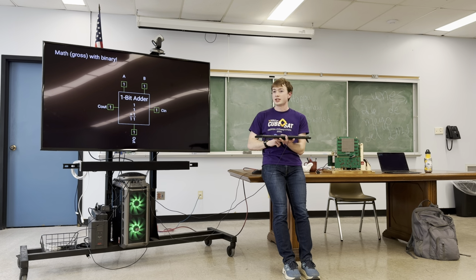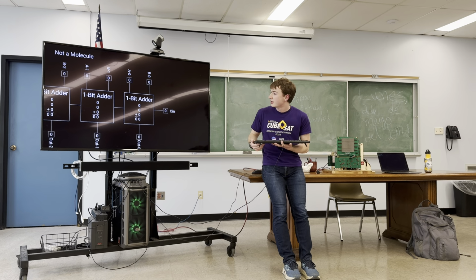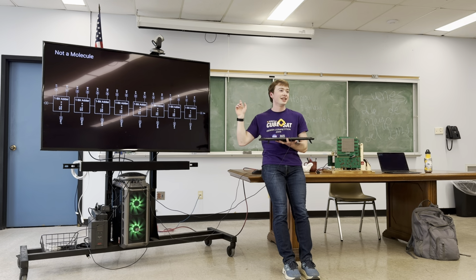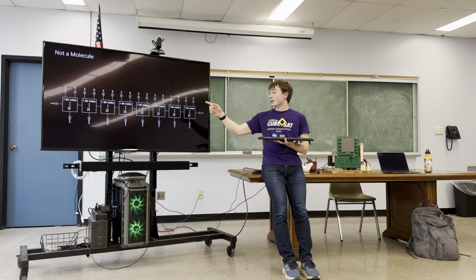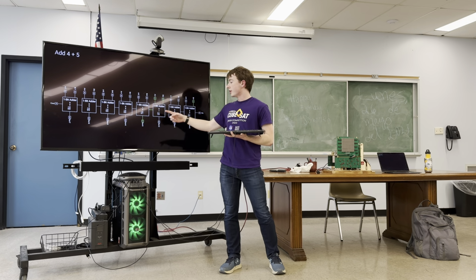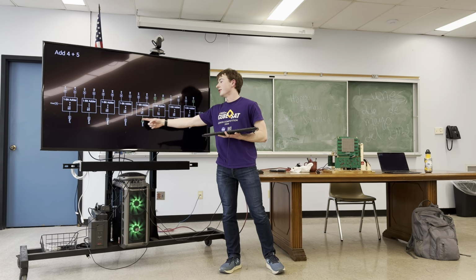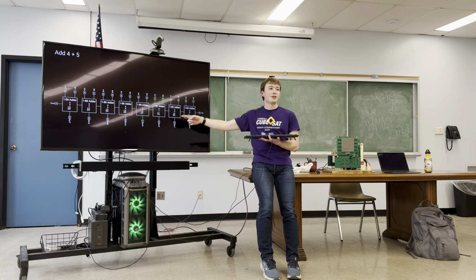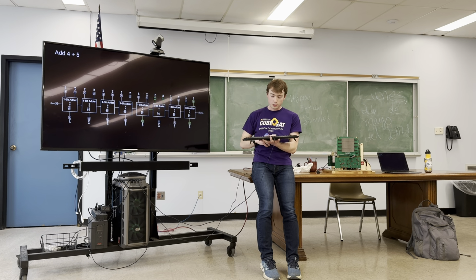And then you can chain these together really easily. Okay, so the carry inputs and outputs are connected together for all of them. And notice how there's still a carry input and output. This can be chained together to make even longer chains. And then, just an example of adding 2 bigger numbers together. So this is output 3. 2 to the third is 8. So that's 8 plus 2 to the 0, 1 times 1, so the output there is 9, which is 4 plus 5.